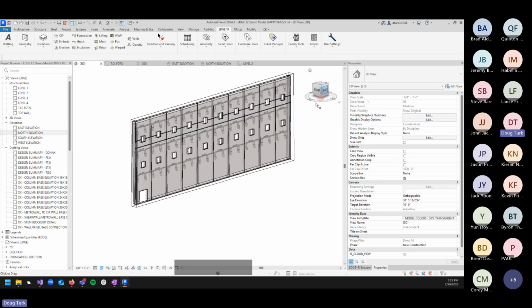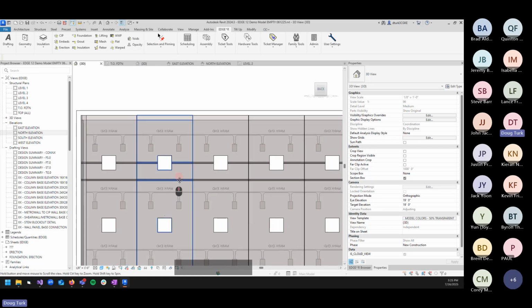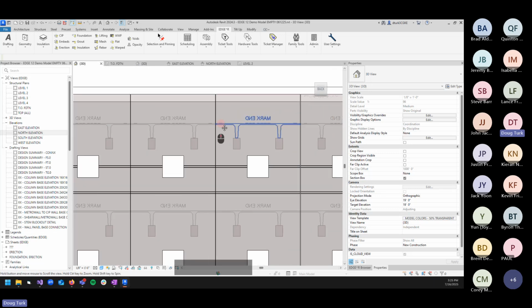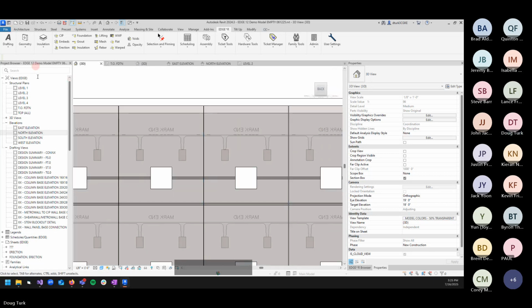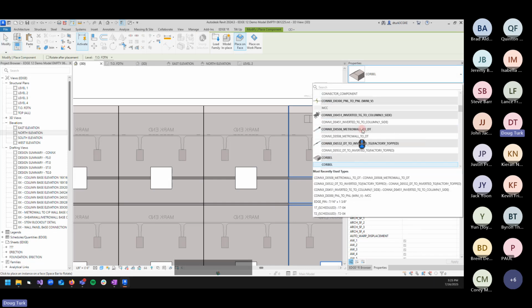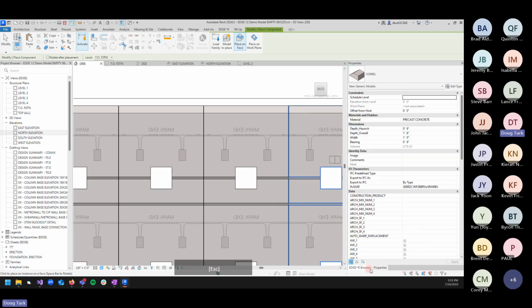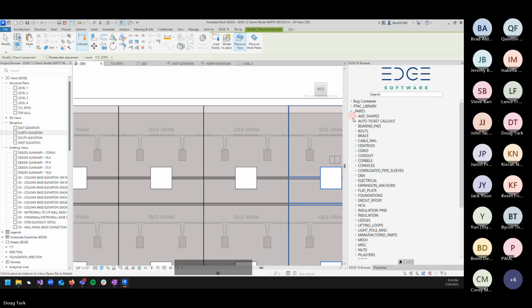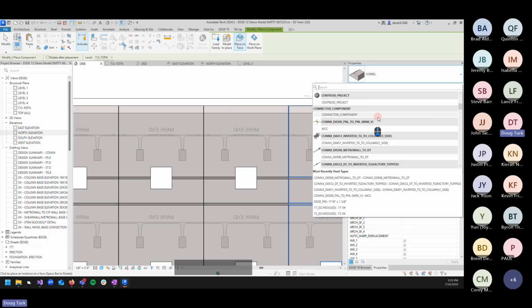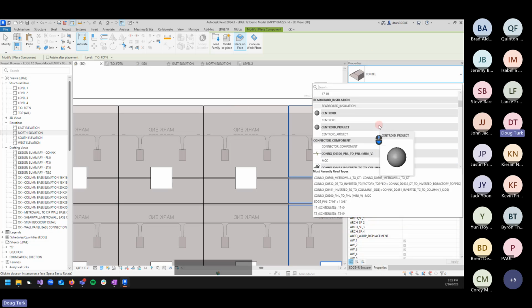And then let's go ahead and add some cornices to the other side. And maybe we'll just do any one of these panels. Maybe we'll do this one. So we're going to go ahead and again grab one of our families. I believe this one I might have to go to the Edge browser for. So we're going to go down here, pull in the add-on cornice. And that will now be loaded into the family. If I can find it.